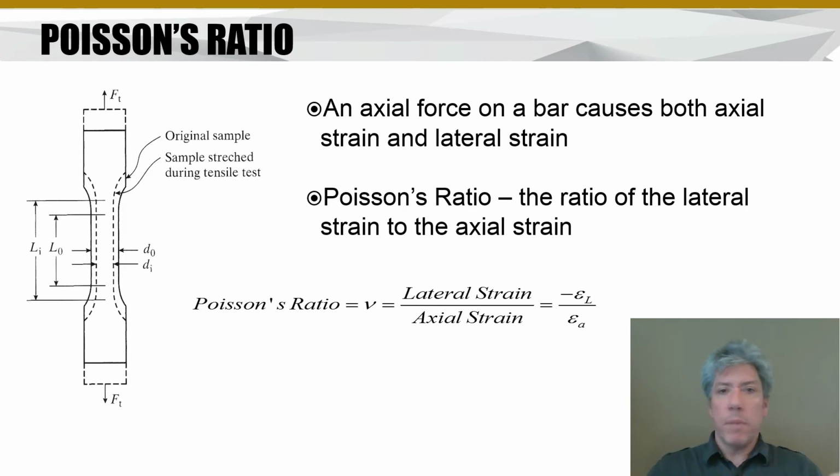So if you think about, maybe you've used a dog bone in a class before where you were testing material samples. When you take that dog bone and you stretch it, it gets longer in length, but that material has to come from somewhere. In other words, the volume that whole sample takes up remains pretty much constant. It turns out with some metals it actually goes down a little bit, but that's not terribly important right now. So as you stretch it and it gets longer this way, it gets more narrow in the lateral directions. And in fact, not only one lateral, but both front and back and left-right laterals go down.